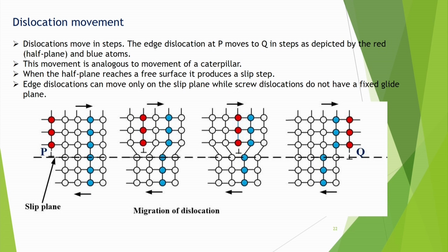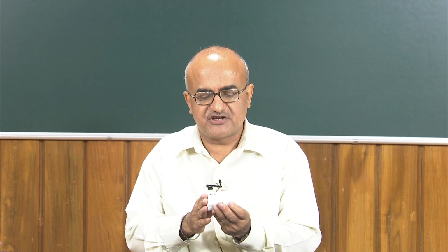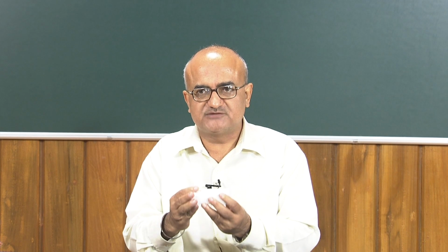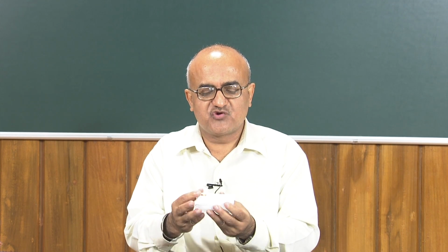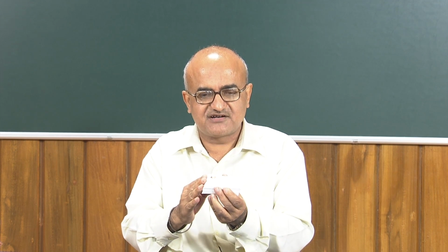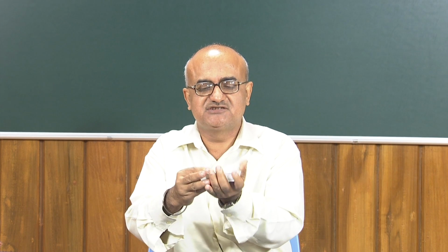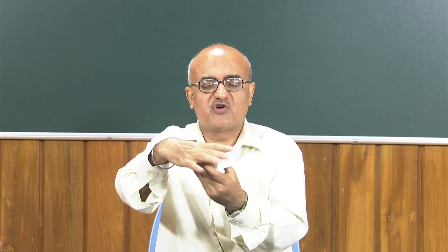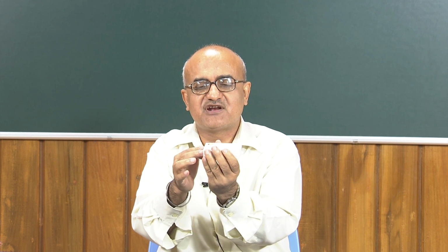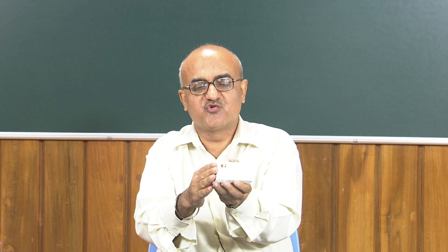So for this dislocation, we sometimes give the analogy that metal deforms, which is why the volume remains constant, because metal deforms like a deck of cards. You can take playing cards. I don't play cards, so I have brought my visiting cards. You see my visiting cards are there. I have stacked them. You consider that atoms are arranged here. Then I am pushing it, and you see that here it is like this. It is going in this way.